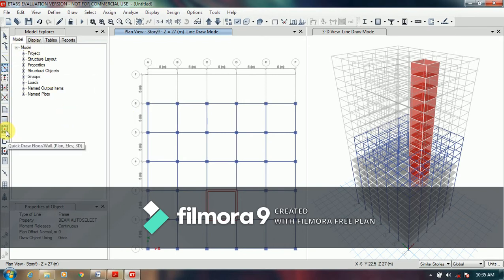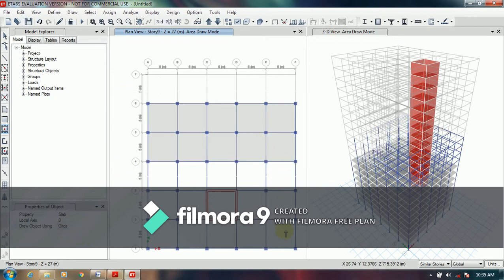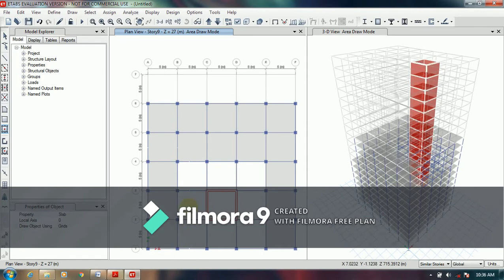So just go to quick draw floor wall plan. Now check the property, it is slab. So now we can draw the slab. Now draw the slab near the shear wall one by one. It will take some time.